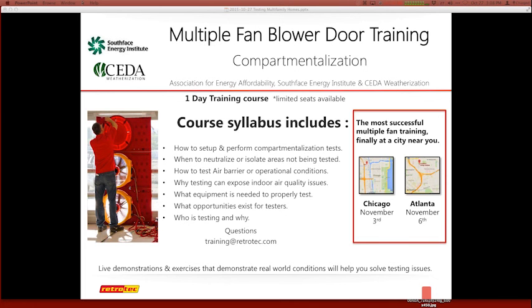The question that Cohn Hoff was asking about how many fans: the method of calculating the number of fans is fairly trivial actually, and our fan calculator does that quite well. What's probably more difficult when you're using multiple fans, like 2 or 3 fans or more, is to know what pressures will be inside the enclosure and where the fans should be distributed. You might need additional fans just to get the proper pressure in different parts of the building. So that becomes more complicated, and the spreadsheet that I mentioned earlier answers that question fairly well.